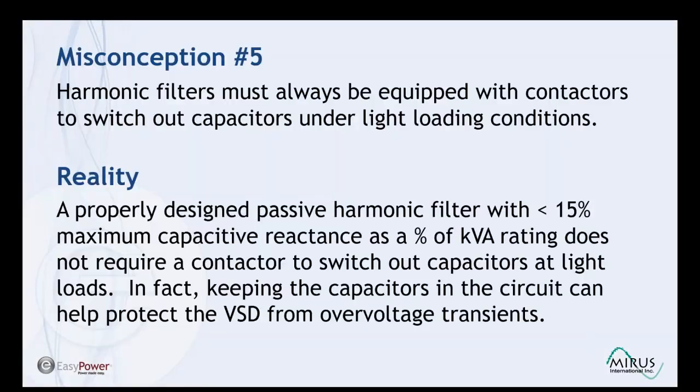So misconception number 5 is that harmonic filters must always be equipped with contactors to switch out capacitors under light loading conditions. The reality is, a properly designed passive harmonic filter with less than 15% maximum capacitive reactance as a percent of its kVA rating does not require a contactor to switch out capacitors at light loads. In fact, keeping the capacitors in the circuit can help protect the VSD from over voltage transients.